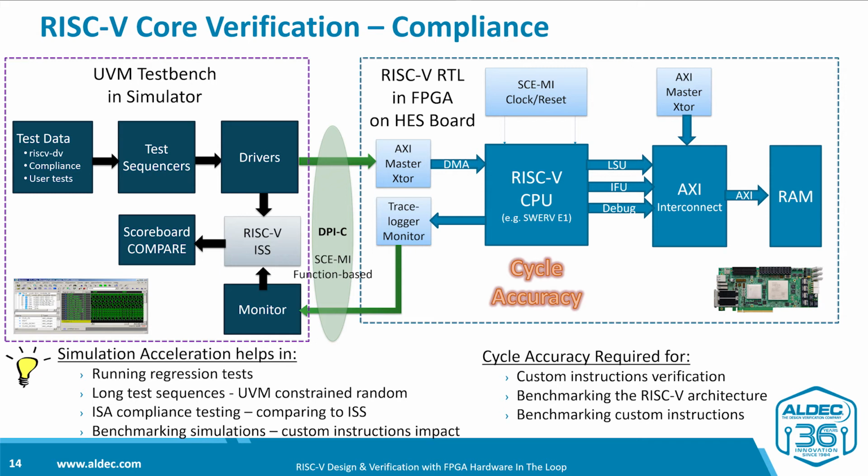Then you can use the same UVM test bench connected to the design running in FPGA, and so you can accelerate the simulation tens or even hundreds of times. I'd like to emphasize also that cycle accuracy is preserved in emulation, which is required for verifying microarchitecture functionality and benchmarking its performance.